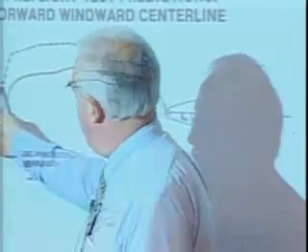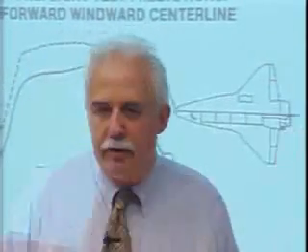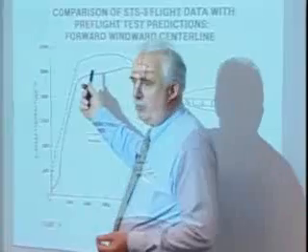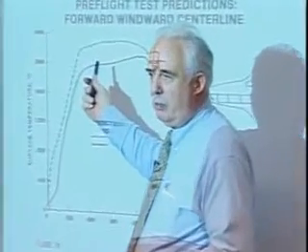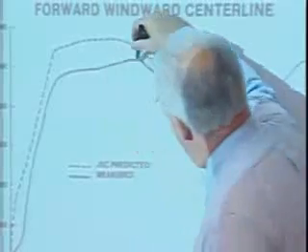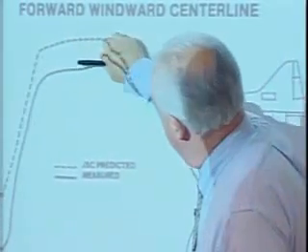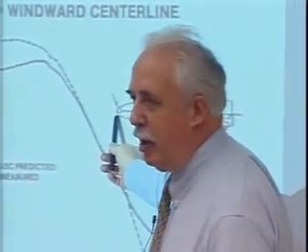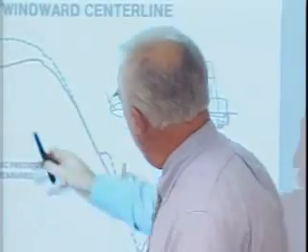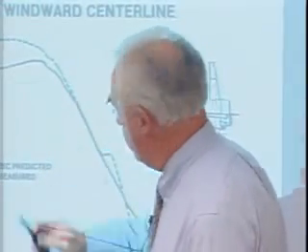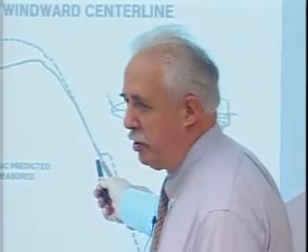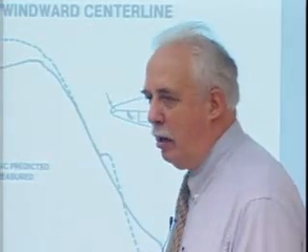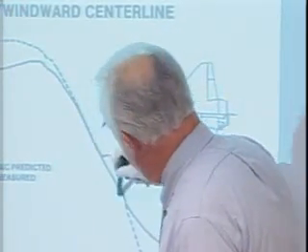Up here is very important. Now, this is temperature, and I just mentioned, epsilon sigma T to the fourth. That means the heat transfer is 4 times as bad. We did a terrible job up here, and I'll get back to that. Now, over here, what happens is I try to stay laminar. I come down, and we predicted, well, this was really a stretch. We never got turbulent heating up on the nose, okay? Way beyond wind tunnel, way beyond our experience base, but the model just went up there. So we really didn't expect that. That was a pretty conservative boundary layer transition. And then, well, son of a gun, the actual temperature is higher than turbulent, even though it would appear to be laminar.